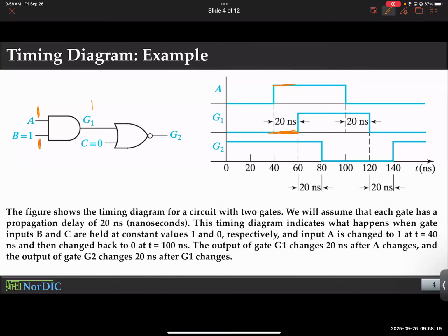Yes, thank you. Did I tell you that there is a delay involved? Your outputs don't instantaneously respond to the input changes. It's not that the input changed and the output changes right away. No, there is a process involved, and interestingly, it all comes down to capacitors. Did I tell you that there are capacitors at the gate? Similarly, there are capacitors at the drain as well. There is a lecture that I teach in 433 called MOSFET capacitances. Basically, MOSFETs are full of capacitors: gate, drain, source, it's everywhere.